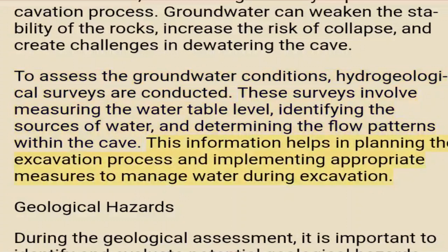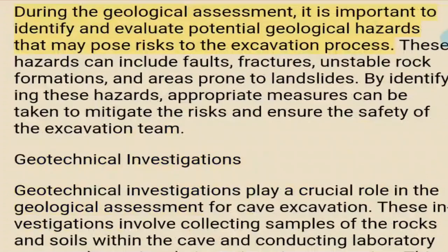This information helps in planning the excavation process and implementing appropriate measures to manage water during excavation. Geological hazards. During the geological assessment, it is important to identify and evaluate potential geological hazards that may pose risks to the excavation process. These hazards can include faults, fractures, unstable rock formations, and areas prone to landslides. By identifying these hazards, appropriate measures can be taken to mitigate the risks and ensure the safety of the excavation